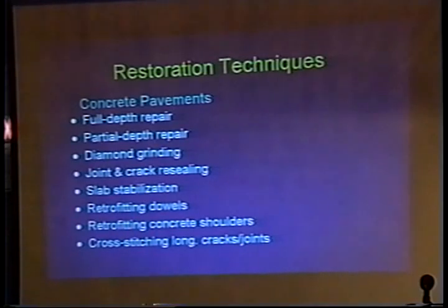Retrofitting dowel bars. There's a project going on right now on I-75 in Findlay, in Hancock County, that has a combination of full depth repair and retrofitting of dowel bars across cracks that have developed in some of the slab panels. It was a longer slab when it was constructed 12, 13 years ago, I think 21 to 27 foot joint spacing.